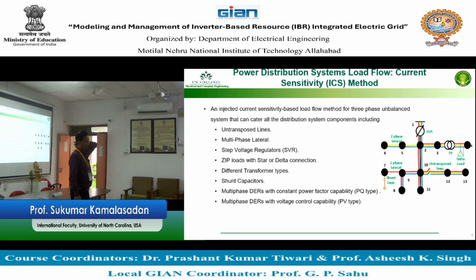Every IBR, when we talk about it, our interest is only on the inverter. Remember? So IBR acting as PQ type means what? This inverter is not delivering any reactive power. It is actually keeping the reactive power or power factor constant at whatever number. It could be 0 or it could be 0.5 or something.